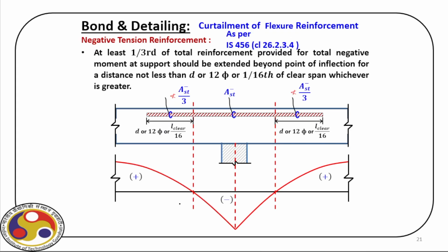Now let us see the negative bending moment, which is hogging at the continuous support. Then we can calculate this still based on the requirement, so this value of M is applied. For that we can find out the amount of steel that is required. Now as we go towards the midspan, obviously the tensile face is on the other side, and this point is the point of contraflexion.